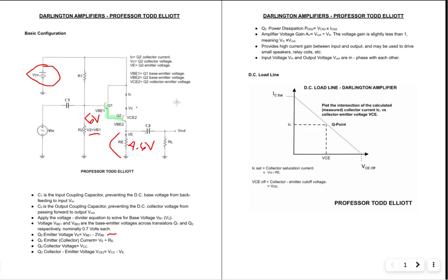Minus 2 diode drops, 2 times 0.7 volts, we arrive at the emitter voltage. Divide that by the emitter resistance. Again, I have other videos on this, much more detail. That gives you the emitter current. Okay. All the key parameters, current and voltage, are marked on the drawing, and I formally identified them for you there. Okay.